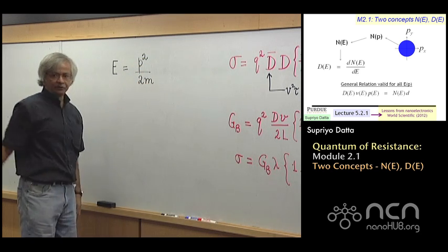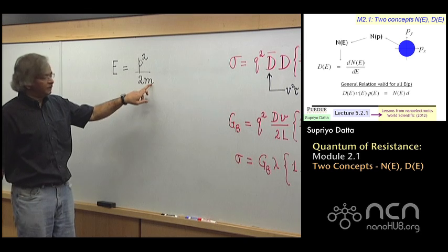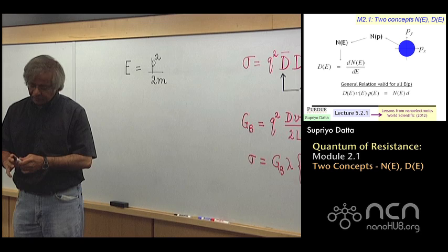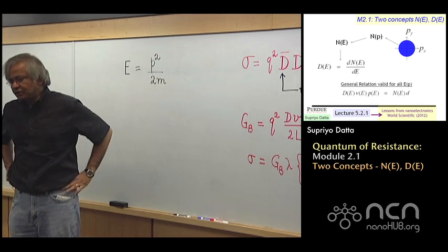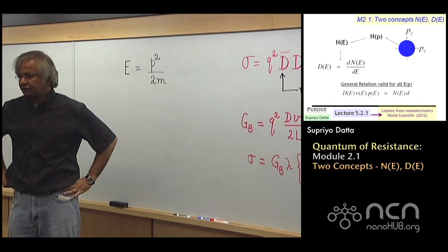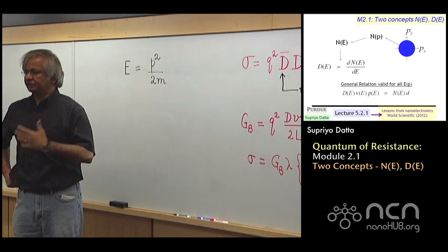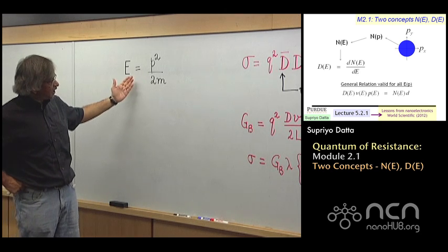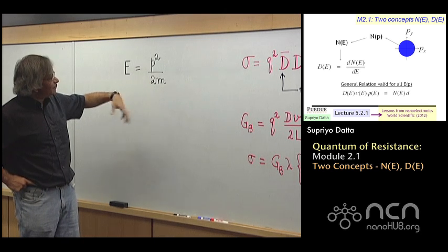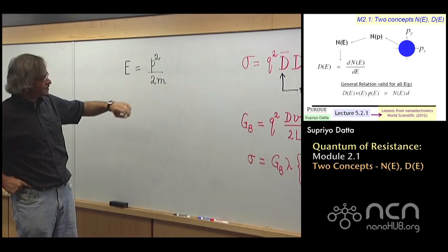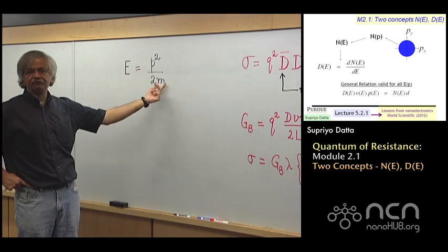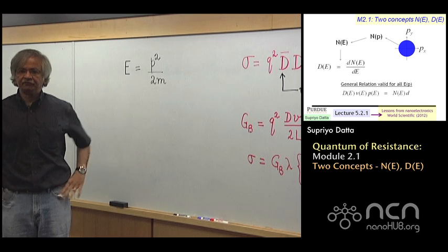And this is in vacuum, where this m would be what we call the free electron mass. One of the very important insights in solid-state physics was that even in complicated solids, like silicon or gallium arsenide, where electrons are moving through this complicated object, it behaves in the energy range of interest as if there's an energy momentum relation like this, but with a somewhat different mass, which people call the effective mass.